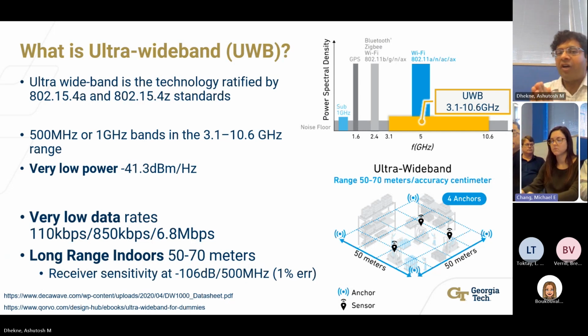However, think of when you have a large bandwidth, what do you gain? You can now construct a signal which lasts for a very, very small amount of time. When you have a lower bandwidth, the signal has to last for a longer time. When you have a higher bandwidth, the signal could last for a much shorter time, which also means that you can send many of these one after another, and you can encode it in a manner such that any other interruptions or interferences can cancel out.